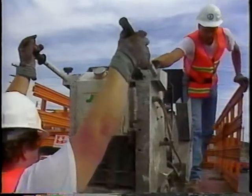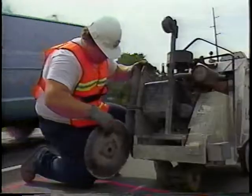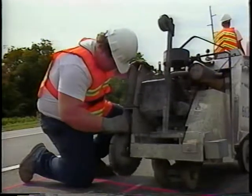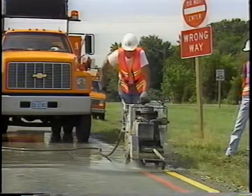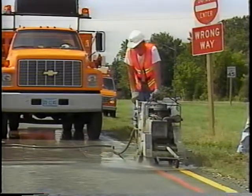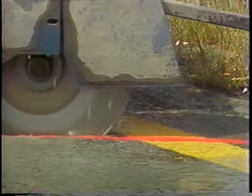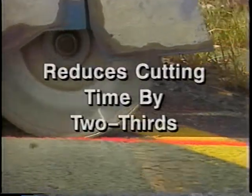Now it's time to saw cut the slot for the loop wire. This is one of the most time-consuming parts of the installation process. There are many saw types and sizes available. Durable diamond blades and fast-cutting high-horsepower saws are recommended. Water cooling the saw blade increases its life and eliminates the irritating, dangerous, dry-cutting dust. Studies have shown that using a diamond blade, a high-horsepower saw, and water cooling reduces cutting time by 2/3 compared to the less expensive dry-cutting system. The slight increase in initial saw costs can be reclaimed in savings of time, labor, and equipment longevity.